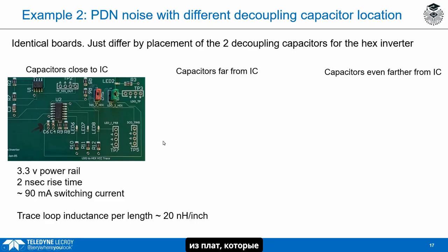So this, again, is one of the boards that I have my students build. The same circuit. Here's our clock. There's an LDO here. I'm just not showing it. Here's the clock. We're going to turn this hex inverter off and on. We're going to switch it. One of the I/O is going to go to a test point, so we're going to trigger the scope so we can tell when it's switching. We got 3 of them that are going to drive some LEDs.